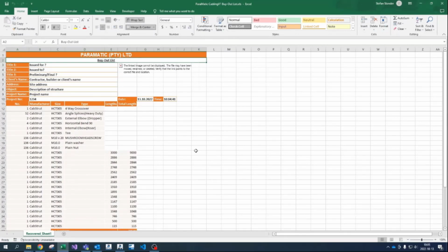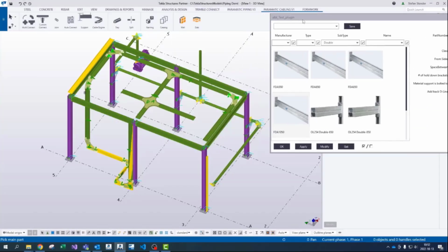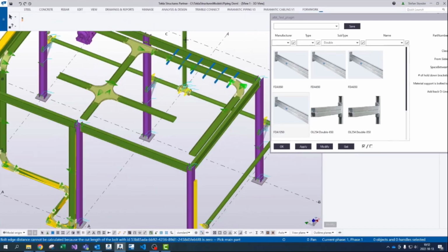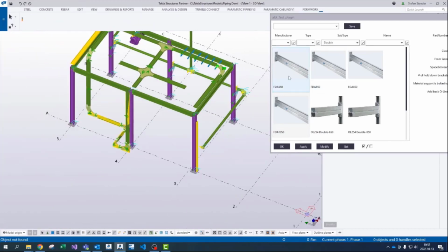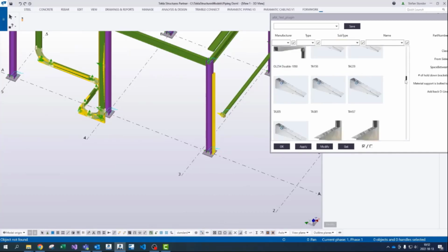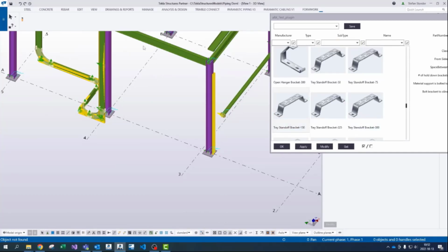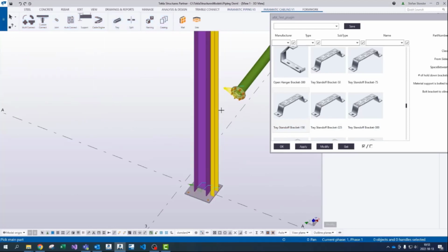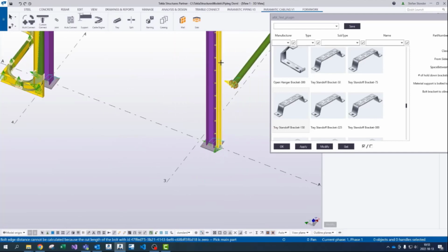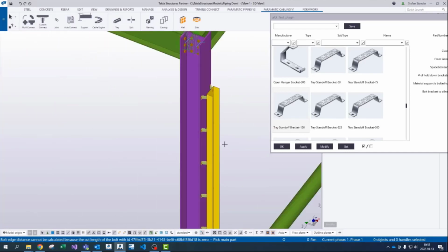But it doesn't end there. We're also able to support the cabling from the structural steel. Now, one of the benefits of supporting cabling from structural steel, if anyone has ever worked with an electrical engineer on site, is that they decide where the cable racking goes and not us. By drilling or pre-drilling the structural steel, we are now able to force them to support the cable racking where they're supposed to. You don't bump your head.